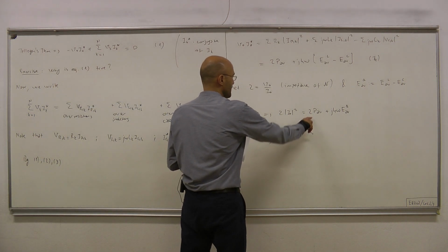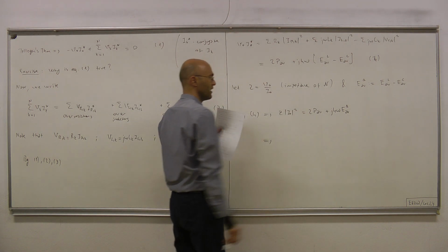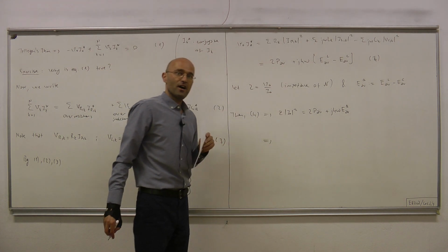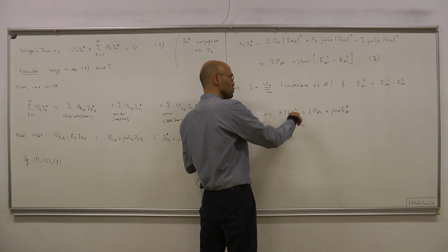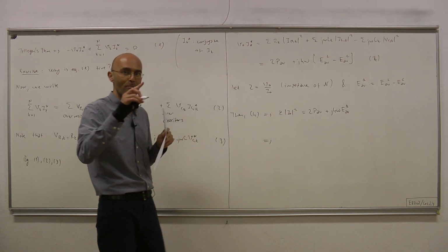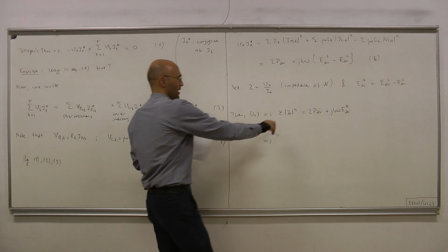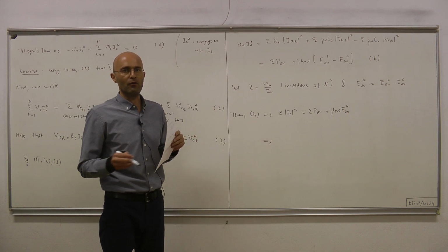And let's get rid of that 2, which we can do by dividing both sides by 2. And then what we have here is I0 magnitude square over 2. And that's I0 magnitude divided by square root of 2 and then squared. And that I0 magnitude divided by square root of 2 is the effective value of the current.